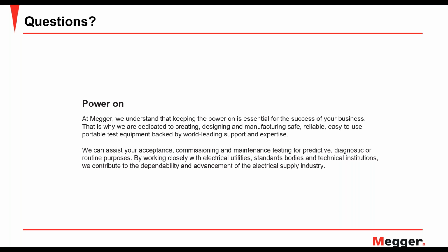And that's no reason to be alarmed. You're just seeing with the test results that it in fact is very dependent on the level of core magnetization, and to recognize what that looks like, and when possible, to demagnetize the transformer and see if that resolves the issue, and the results are comparing better.